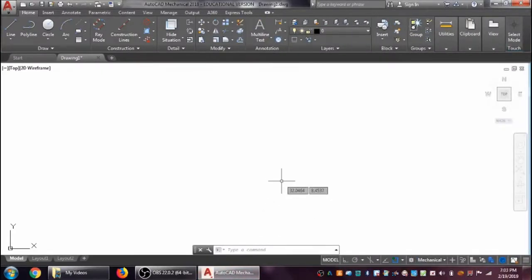Alright, today we're going to start to draw some construction lines, and then we'll put a few horizontal lines to start to identify what I call the ABC of lines. That's our object line and our hidden lines, construction lines, and so forth. And then we'll label those, but we're going to use the layers property manager to identify and make these different line types, and see how the layers property manager is actually used a little bit too.